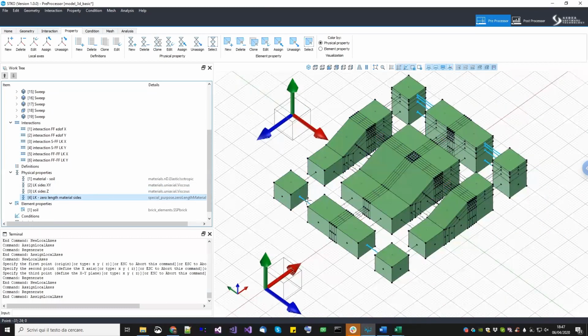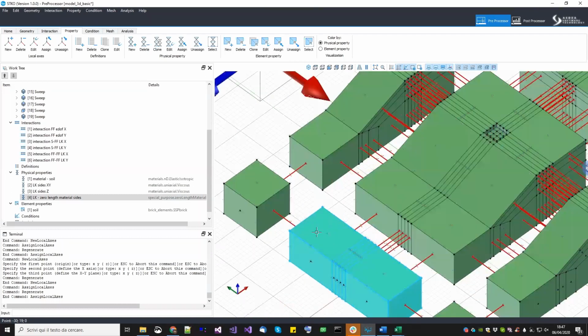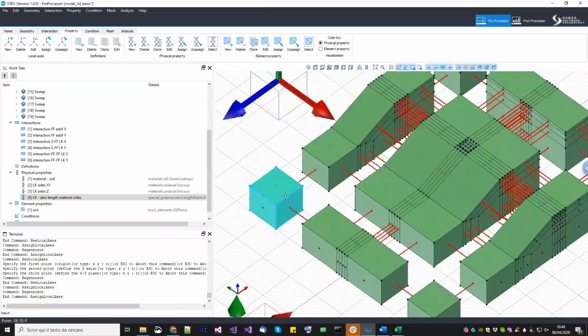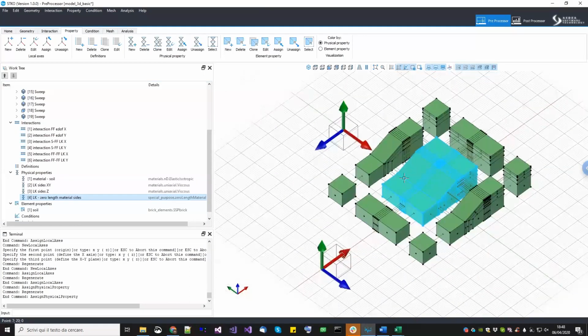Okay. So now I just want to select all of them, both those connecting the soil and the lateral free field, and those connecting the lateral free fields and the corner free fields. They share the same Lysmer-Kuhlemeyer material model because I assigned the same material model in every component, of course. Now, you know very well that if I have different soil layers with different material models, I need to create different Lysmer-Kuhlemeyer conditions. So I can drag and drop this. And of course, I don't need to see local axis anymore, so I can switch them off.